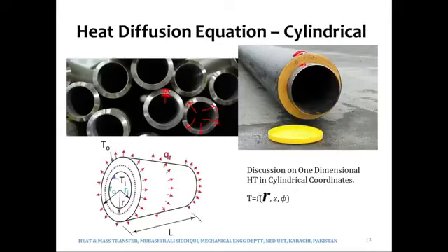So over here the temperature will reduce a lot from 300 degrees Celsius to about 30-35 degrees Celsius, almost the outer environment temperature. It means that there would be a large temperature gradient, a large temperature difference across this thickness of insulation. Why? Because insulation is an insulator. It is not a conductor. So it will offer very high resistance to heat flow. Therefore, there would be a large temperature drop.